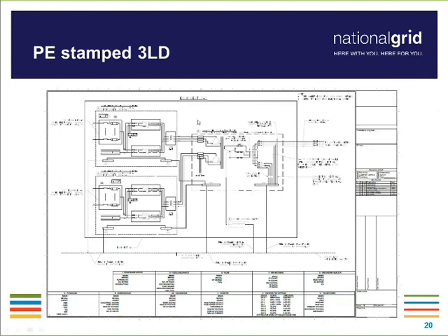Showing it on a three-line would really clearly depict the wiring configuration, especially when it comes to instrumentation transformers that have to be either Y-grounded or connected in some other fashion, maybe a broken delta. When the transformer is connected, you can see that this transformer is Y impedance grounded with two delta secondary windings. So that kind of information is clearly depicted with the three-line diagram, and would not necessarily be discernible from a single line, to where if there's an error or some kind of omission made, we may not pick up on it, or it may be missed or misconstrued.